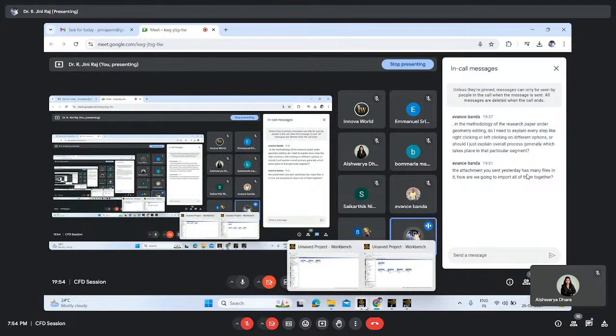Initially we will go with CL and CD. For 1 lakh elements you are getting 0.424; for 2 lakh elements your CL value may reduce, or sometimes it may increase. So we should go with a minimum of 4 element sizes, and the total cumulative elements should increase.